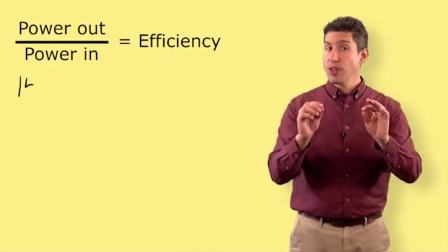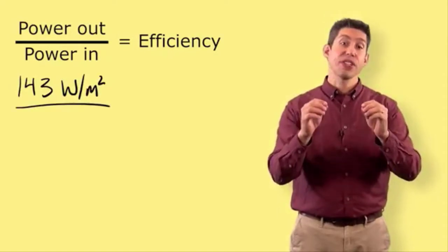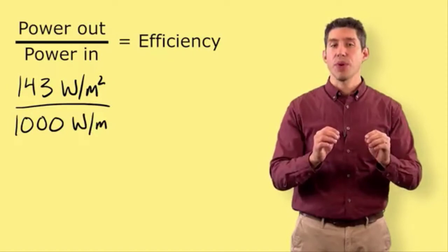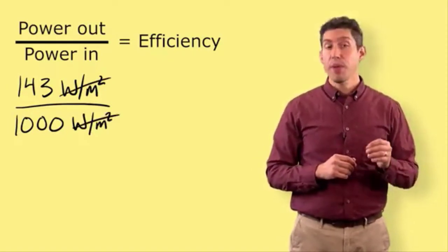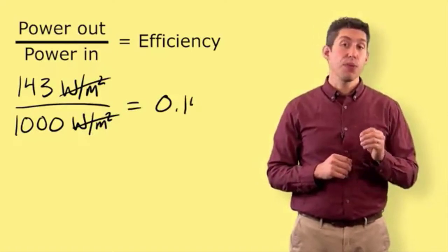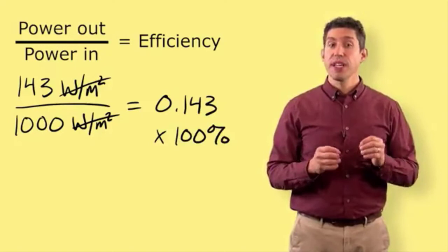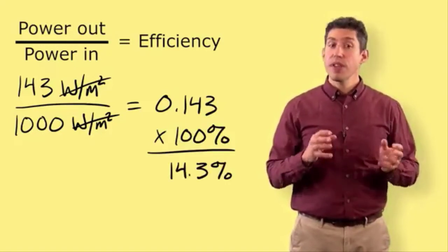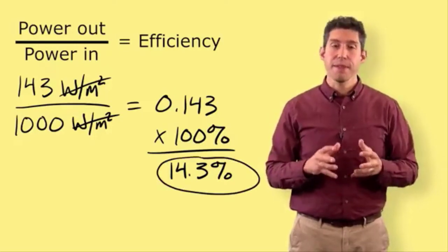So we take 143 watts per square meter in electrical output and divide that by our standard test condition solar input, which is 1,000 watts per square meter. When we divide these two by each other, the units cancel out and we get a decimal value of 0.143. Converting that to a percentage gives us 14.3%. So this solar panel would have an efficiency rating of 14.3%.